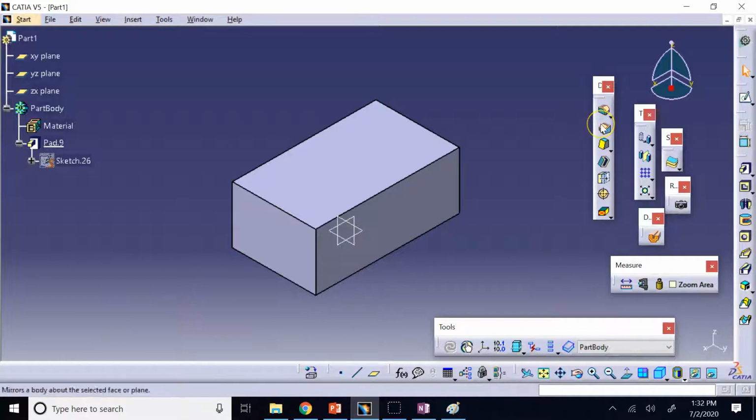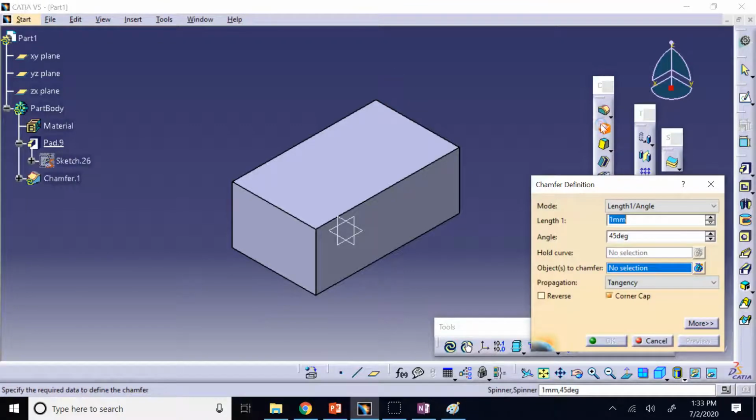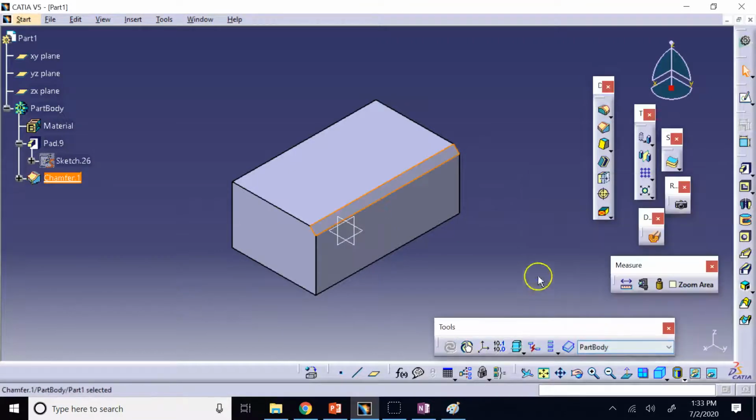The other way, as I told you, to get rid of a sharp edge is chamfer, which is cutting it with an inclined surface, basically. So again, you can do it on a whole surface, so all edges will be chamfered, or on a specific edge. And then here you provide the diagonal length, and then you provide the angle, and there we go. The chamfer. Okay, so that is another tool for getting rid of sharp edges.